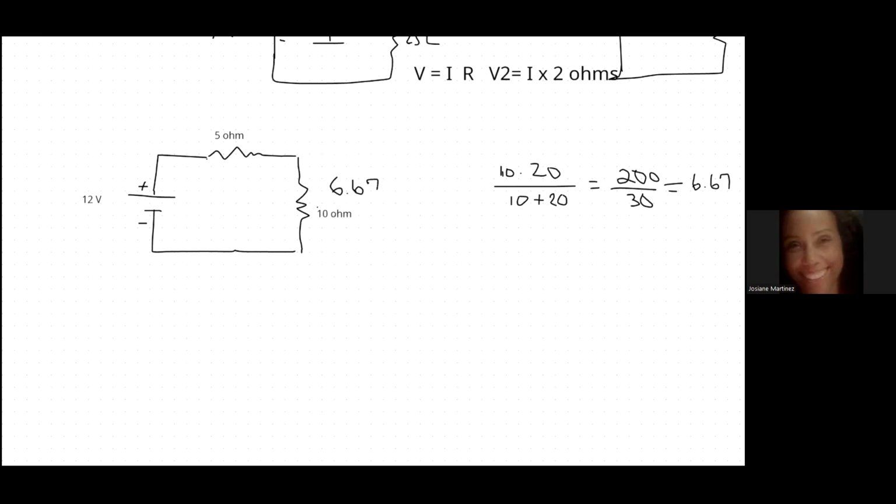So you need to realize that an equivalent resistor means that if I were to look at the previous parallel system with the two branches, and I made it a black box, it would look just like I had one 6.67 ohm resistor in that whole box. The currents and the voltages will be the same.